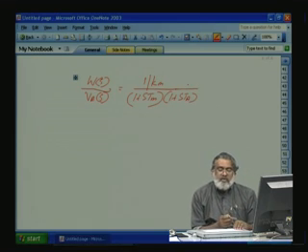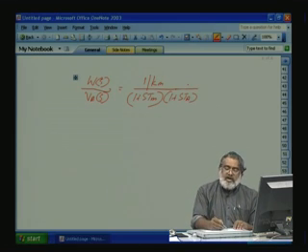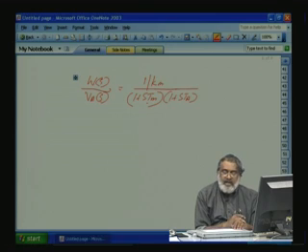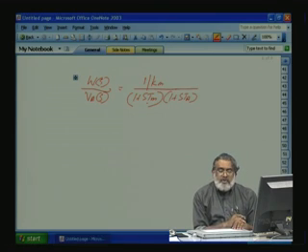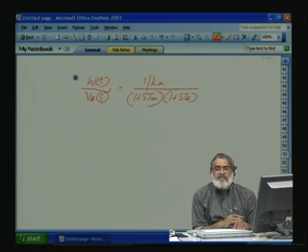So, if you are controlling the speed omega s with the Va, the response of the machine depends on two time constants. One is the armature time constant Ta, one is the electromechanical time constant Tm. So, these two Tm and Ta will determine the response of the system. These are the time constants of the system.